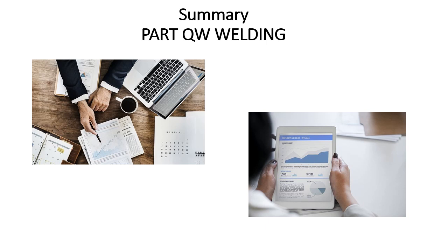So basically we covered welding positions, and the breakout of how ASME Section 9, Article QW, is broken out. It covers welding qualifications. We talked about groove welds. We talked about how the people that qualify the welds need to be responsible for them. You need to keep documentation on your welds and your procedures and your personnel. All that's laid out in Article 1. It's the basic foundation rule book and then a bunch of definitions.